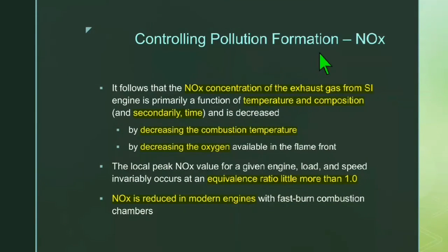Controlling pollution formation (NOx). It follows that the NOx concentration of the exhaust gas from SI engine is primarily a function of temperature and composition and secondarily time, and is decreased by decreasing the combustion temperature, by decreasing the oxygen available in the flame front. The total peak NOx value for a given engine load and speed invariably occurs at an equivalence ratio little more than 1.0. NOx is reduced in modern engines with fast burn combustion chambers.